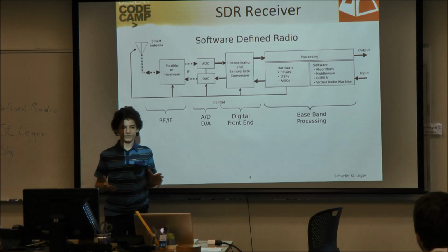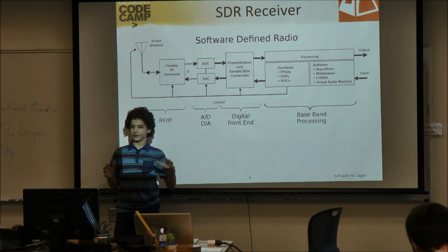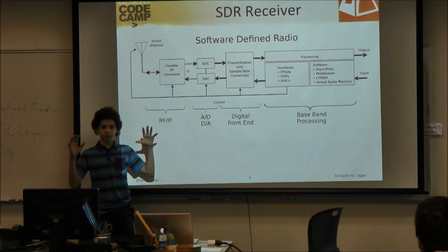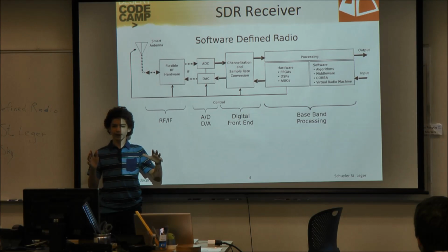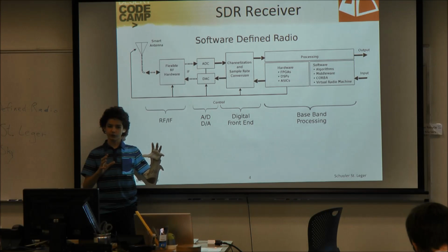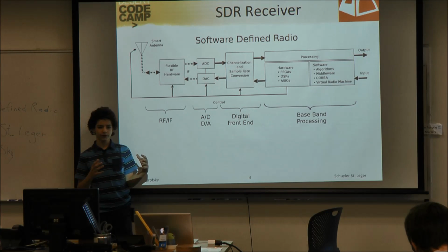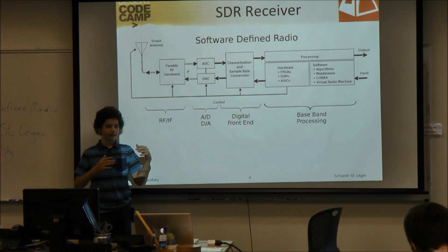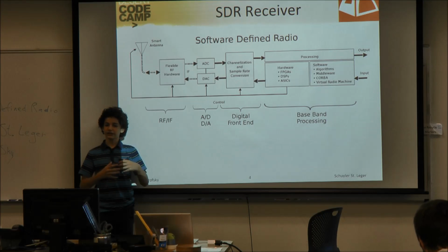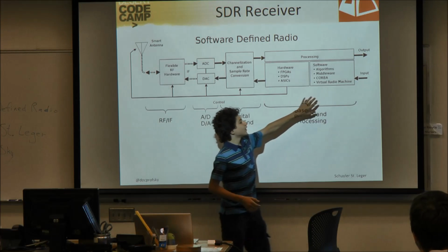Okay, so an FPGA is a device that you can use software to make hardware with. It stands for Field Programmable Gate Array. Essentially what it means is you write a program that represents more hardware than software, and when you program it, it will reconfigure logic elements to do it. So typically you'll use it to do high-speed things because it's more hardware, but also if you're doing lots of complex signal processing, you can do it in them. But then eventually it goes to your computer.